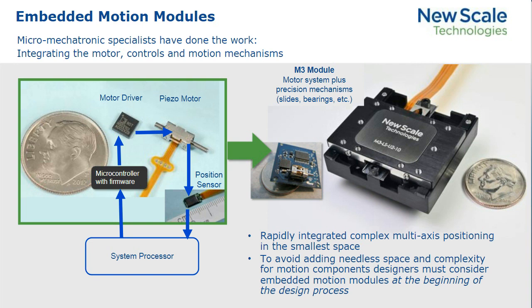Now, how do these fit in the universe of motors? The simplest way to think about it is if your application requires a motor that's smaller than 6 millimeters in diameter, that's where piezoelectric motors can really start to contribute. They have higher torque density, fewer parts, and higher force density. There's one takeaway from today I want you to leave with: at NewScale, our piezoelectric motors all operate at battery voltage.